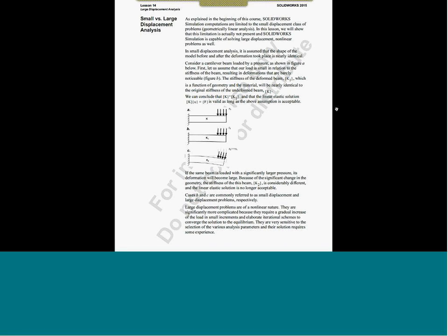You need to move into non-linear analysis. This kind of non-linearity, wherein the displacement is large, is called geometric non-linearity. When this comes into the picture, there are many different effects that happen inside the material. One is something called stress stiffening.